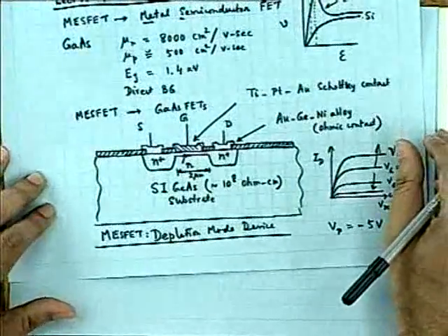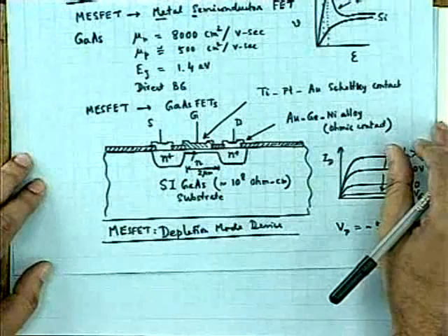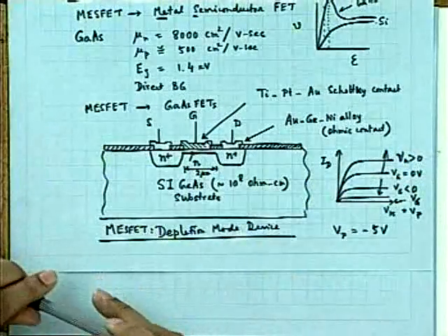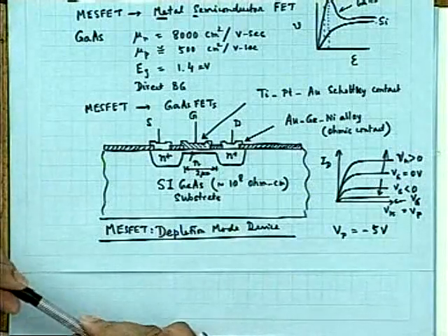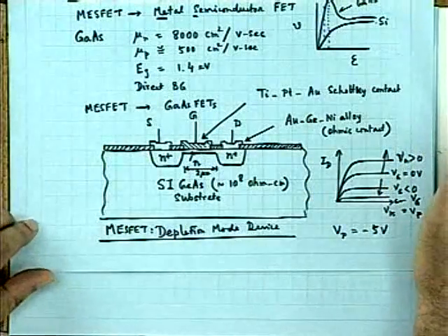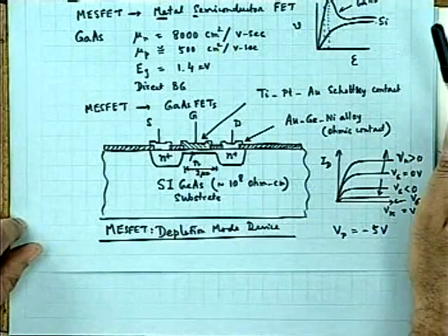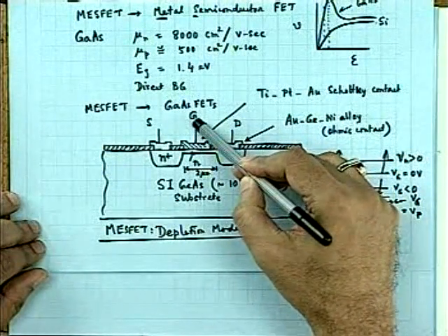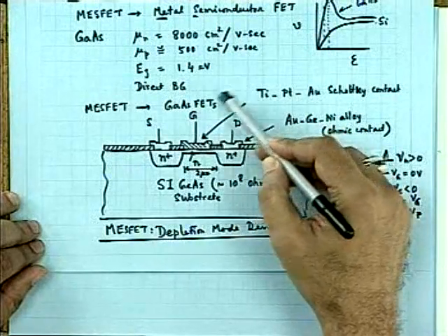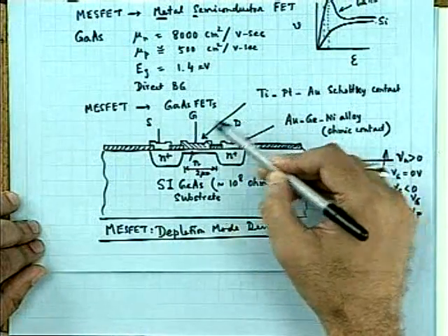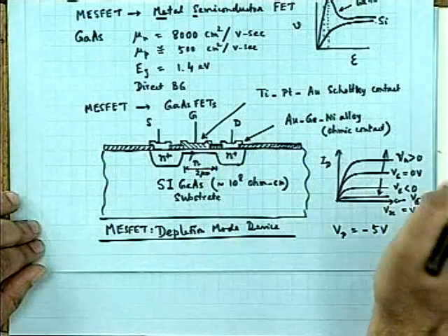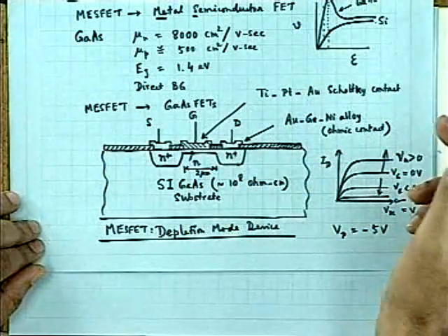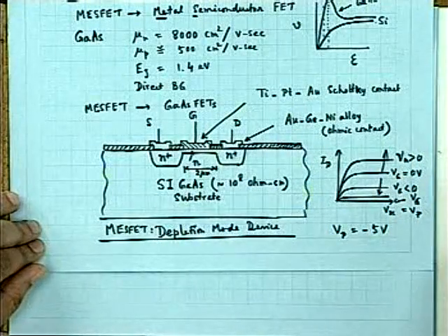I have mentioned so many times in the class, when you design a logic circuit, do you think that depletion mode MOSFETs or MESFETs are highly desirable? Because here the gate voltage requirement is negative, 0 to negative for switching it off, whereas the drain voltage is positive. So the output of an inverter cannot be directly connected to the input of another inverter.